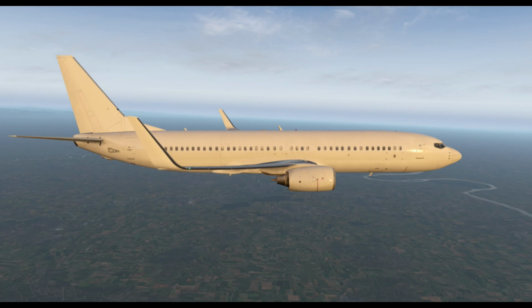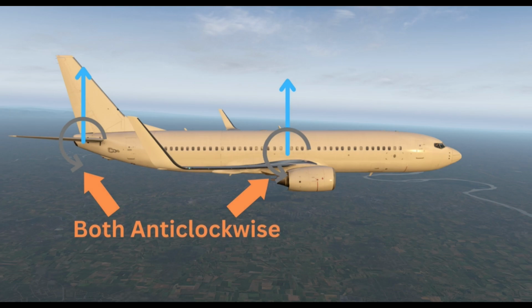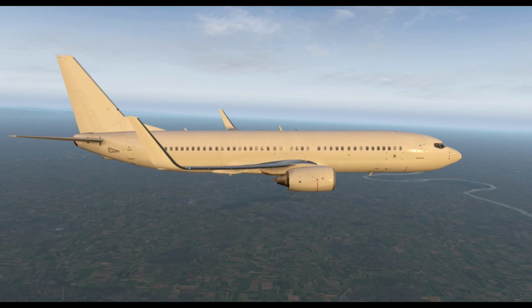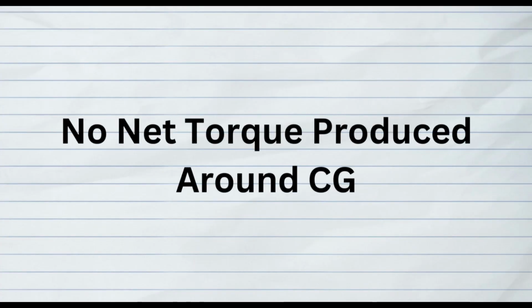In order to trim an aircraft, a balance must be found between the lift generated by the wings and tail. If both produce positive lift, then the aircraft is impossible to trim, due to two anticlockwise torques being created, and not being able to cancel themselves out. Therefore, if the wings produce a positive lift and create an anticlockwise torque around the center of gravity, then the tail must produce an equivalent but negative lift, counteracting the torque with the clockwise twisting force. This would lead to no net torque being present around the center of gravity.